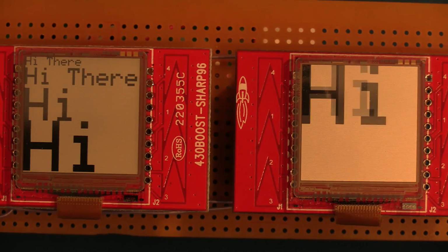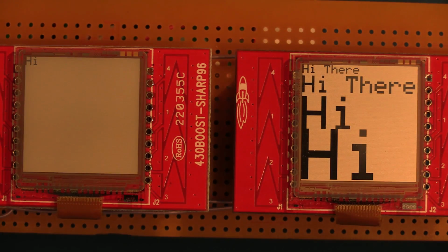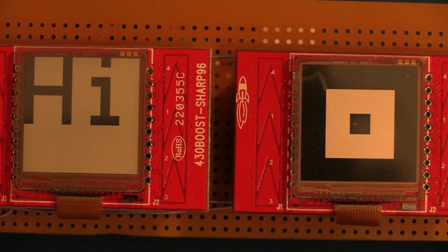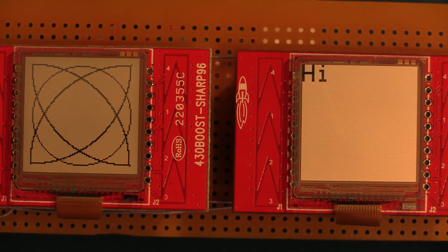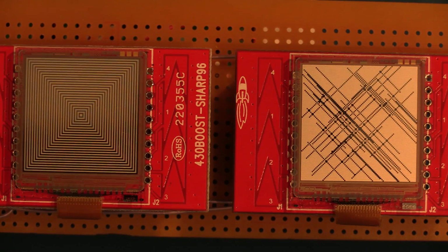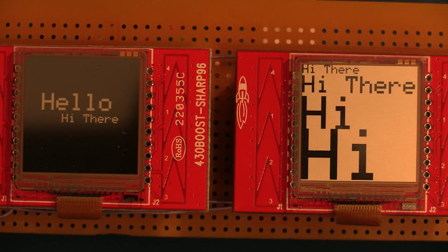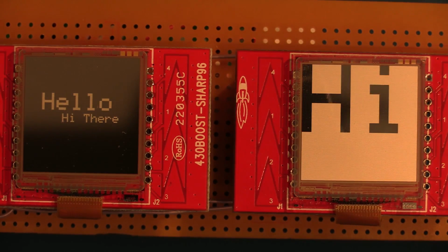So I'm going to slow that back down again a little bit. That's down to just over 1 second thereabouts. So that's now 1 second between each hop. Now I'm not flushing the buffers out to the display for every single pixel that I write on the screen. That would be just silly. What I'm doing is I'm drawing the screen that I want, and when I've drawn the particular screen in memory, then I serialize it out to the screen via this SPI bus. So the actual update on the screen is almost instantaneous. And as I say, we'll do a timing a little bit later, or very shortly anyway. So that's the rolling demo.